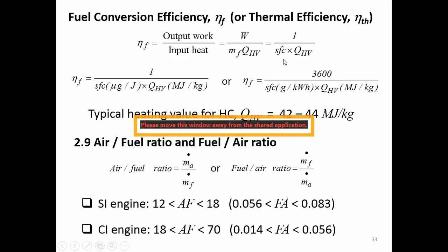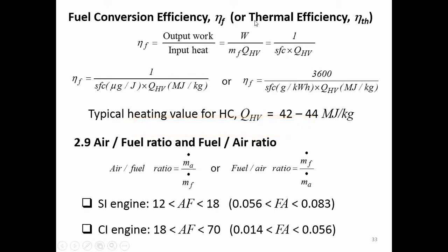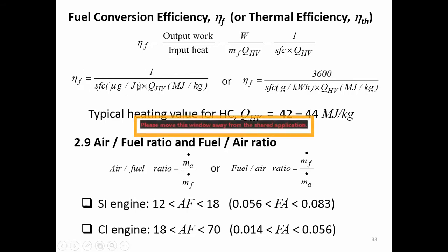So with SFC and the heating value, we can come up with the fuel conversion efficiency, or the thermal efficiency. Okay, and in here, I give you 2 units of the parameter that can come up with the fuel conversion efficiency. We have SFC and the heating value here.